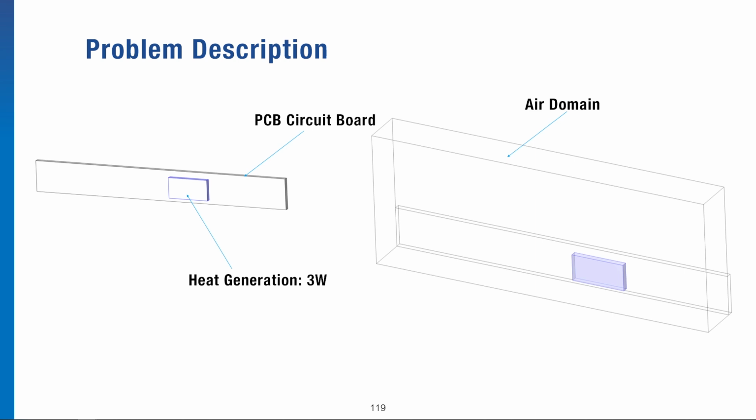This is the basis for building such a model. Simply put, it's like this. A fluid at a certain temperature flows over the surface of a solid. There is a temperature difference between the fluid and the solid surface. In this process, as the fluid flows, its temperature will change. There is a heat transfer process occurring between the solid and the fluid. And this heat transfer process is strongly correlated with the flow conditions. In other words, there will be a convective heat transfer coefficient in this process. That's why it's called conjugate heat transfer.